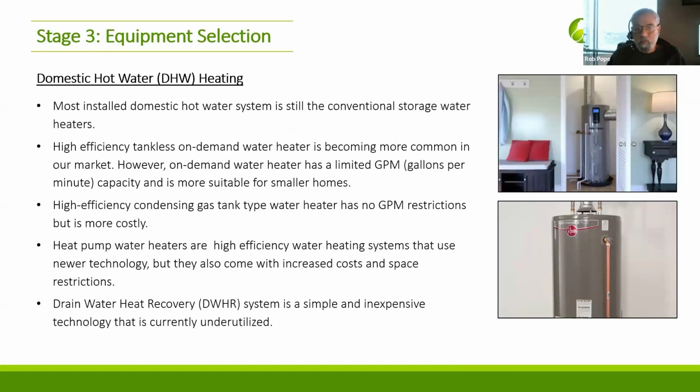Domestic hot water, there are a few choices. These days, we're not going to see that picture on the bottom anymore, the old conventional gas hot water tank with the draft hood. We're going to see heat pump hot water heaters like the other photograph. On-demand ones, if the demand is small enough, because there's a limitation on what you can do with on-demand. You've got to be careful about that. Electric water tanks, nothing wrong with them. There are some really good quality ones out there. There are a few choices with domestic hot water.